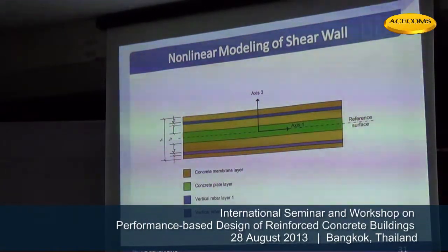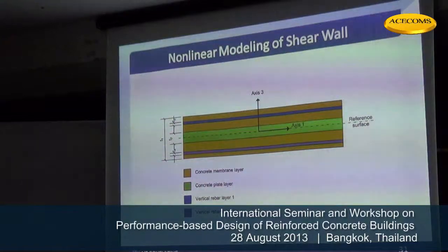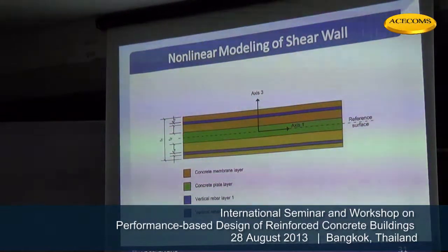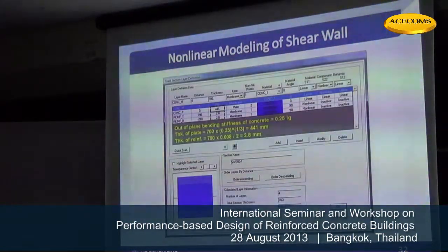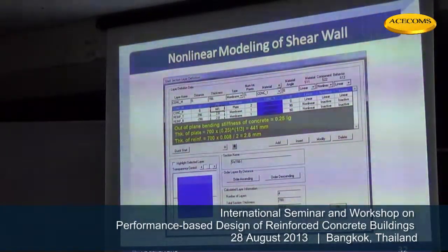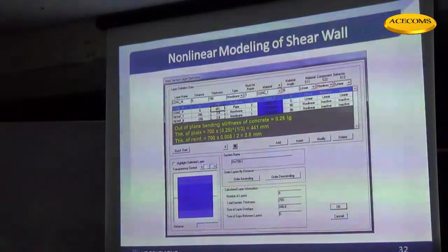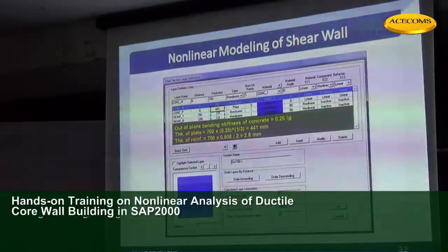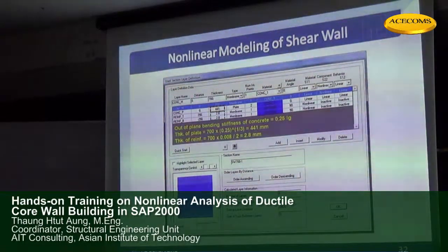So the load comes from the tower, and this is the retaining wall. This is the soil spring. So this diaphragm will act as one beam with a point load in the middle. There will be a lot of tension stresses in this zone, and the compression stress will be in this zone. So we have to check this flexural behavior of the diaphragm.